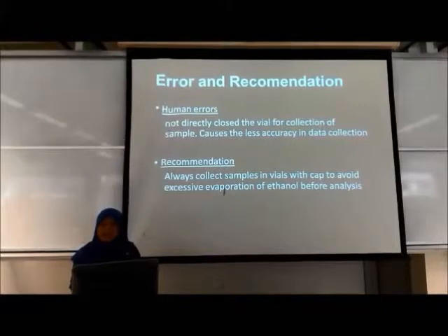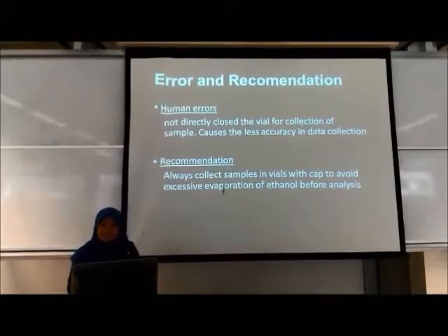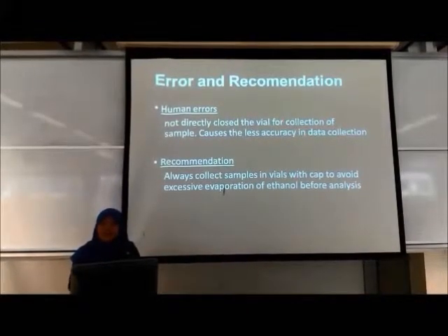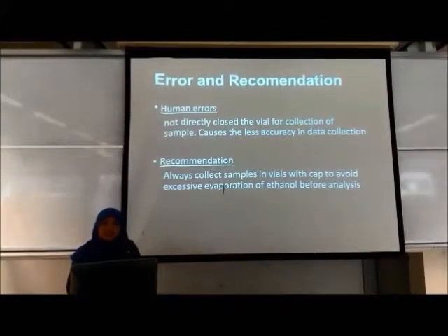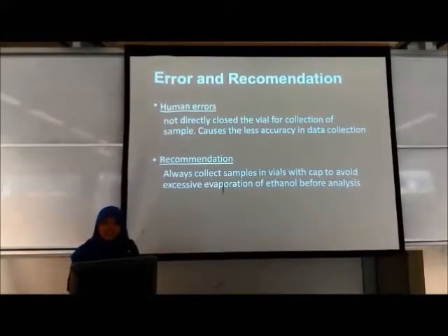From experiment A, we know that the higher the heating power, the more theoretical plates there are, and the smaller the HETP is. A smaller HETP indicates a smaller column height and a more efficient column.